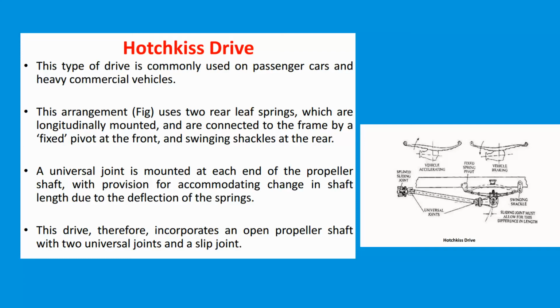It uses universal joints at both ends of the drive shaft, which is not enclosed. The use of two universal joints properly phased and with parallel alignment of the drive and driven shaft allows the use of a simple cross type universal.